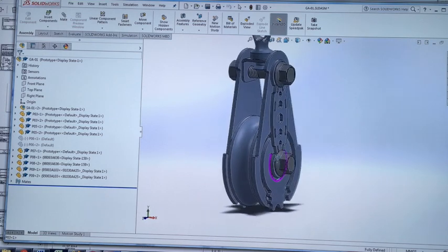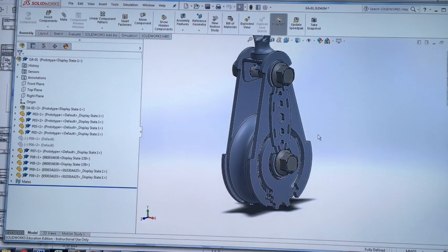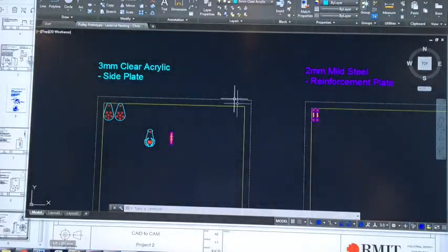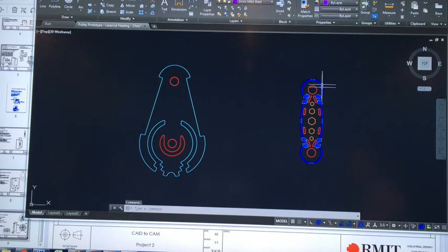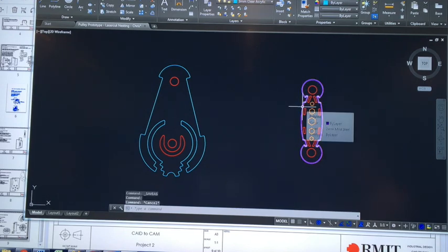Hey Chris, you saying something before about not wanting splines? Yeah, when you're saving your DXF, press Options, and then press the box that says Save All Splines as Polylines. Okay, cool. So we can use splines as a tool? You can when designing, but when you're editing it in AutoCAD, you need to make sure it's saved so that you're able to get it as one complete profile. If you can't, then you need to edit or manually remove those lines to create new ones so you can join them up.